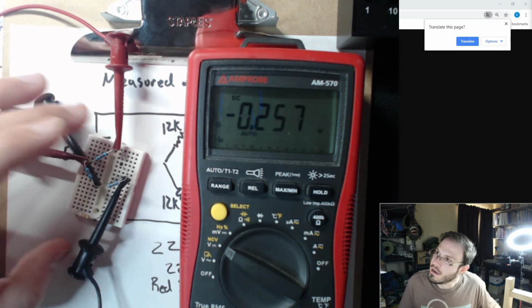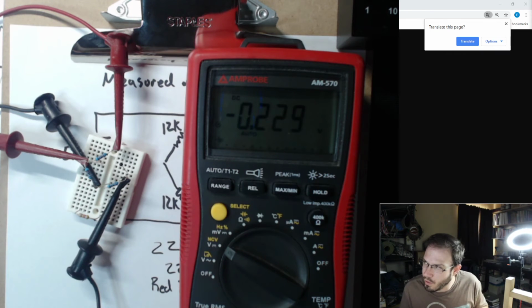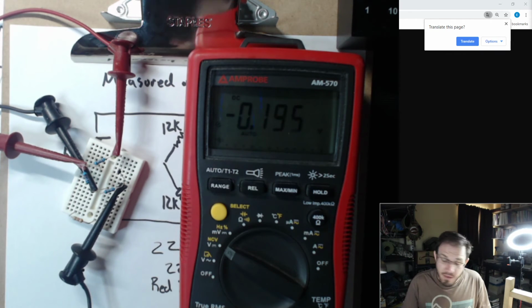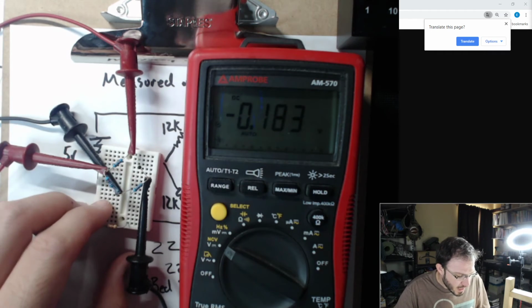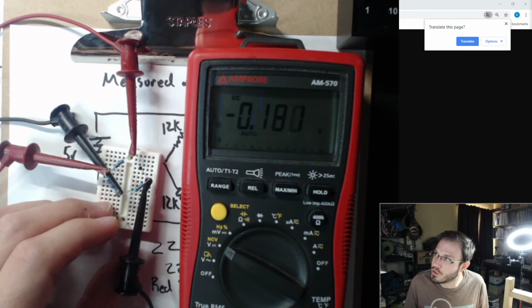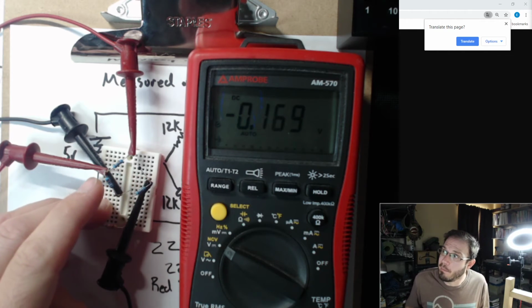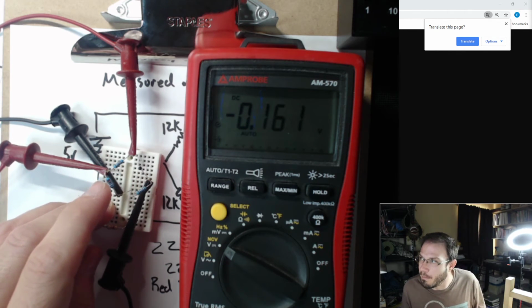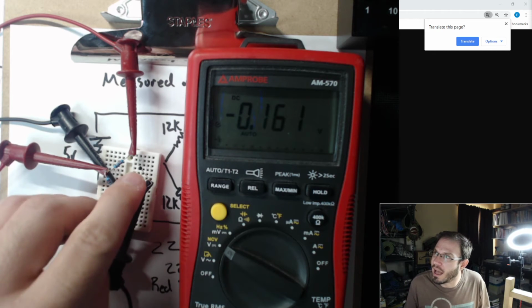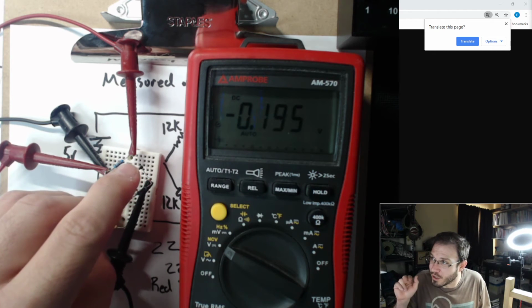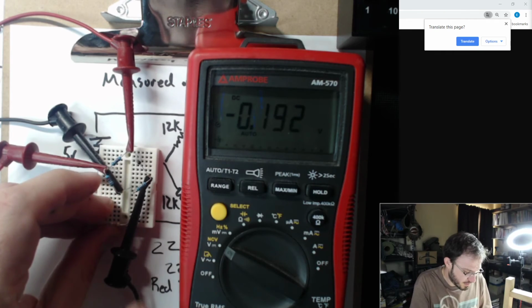Okay, so somebody had previously asked the question, is there a time when I want this bridge circuit to be unbalanced? Yeah, absolutely. If I'm using a Wheatstone bridge as part of my sensor circuit, then I want it to be unbalanced, because that unbalance is what's going to allow me to take the measurement of my unknown resistor, my sensor.